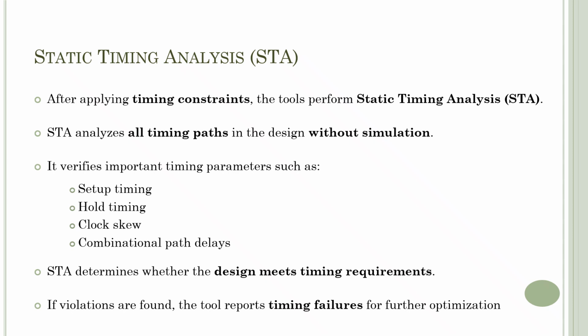In STA, the tool checks every timing path in the design, typically from one flip-flop to another flip-flop, from input to flip-flop, or from flip-flop to output. For each of these paths, the tool calculates how long it takes for a signal to propagate through the combinational logic and routing.